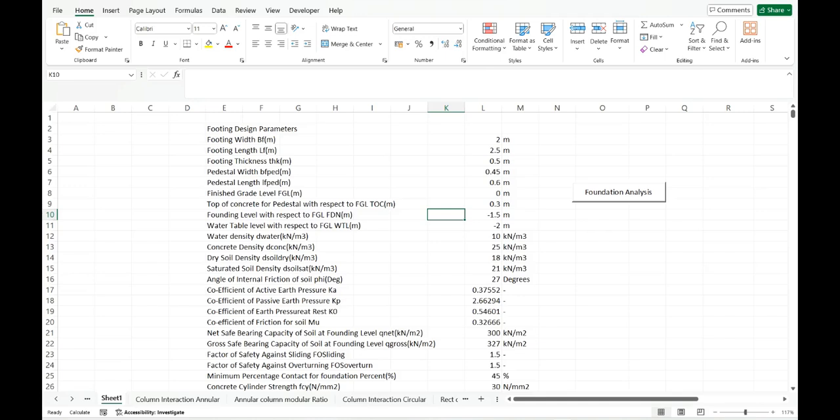It is as follows. Maximum bearing pressure under ultimate load combination is selected. The net ultimate bearing pressure is calculated after deducting soil overburden and foundation self weight with appropriate load factor. Shear force per unit width at effective depth from face of pedestal is calculated by considering the above calculated net pressure as uniform load. Based on this shear force, one-way shear stress is calculated and compared with allowable shear stress based on concrete cylinder strength as per ACI 318 provisions.